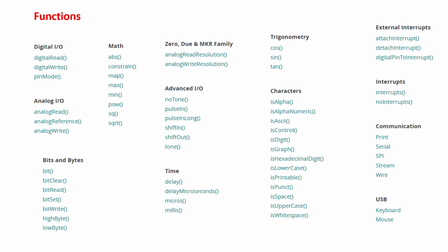If it is digital, we will represent from 0 to 13, that is nothing but 14 digital pins present for Arduino. Whereas for Node MCU, we will represent as D1, D2, D3, D4 and so on, based on the number of digital GPIO pins.